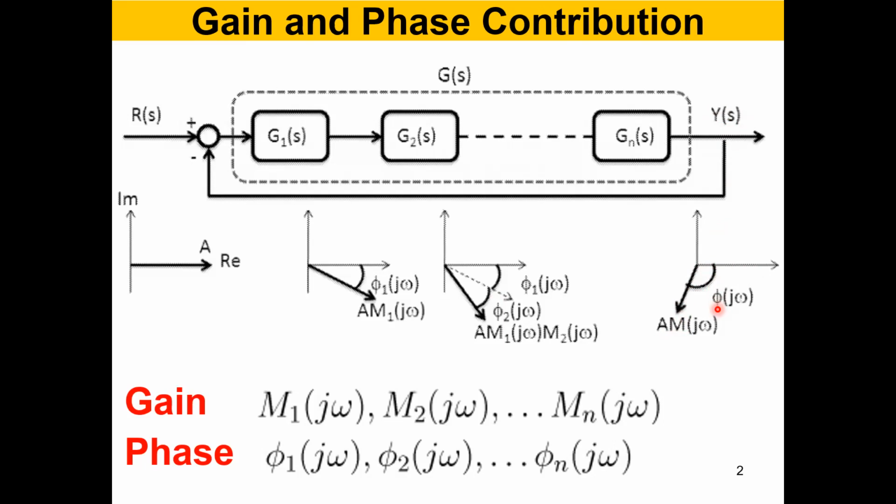Oh, if this attenuation or amplification is acceptable, and if this phase delay is also acceptable, then there's no problem. Okay. So this is actually very clear now, right? We need to look at this frequency based attenuation and phase delay, and this frequency omega will represent all of the frequencies of interest.